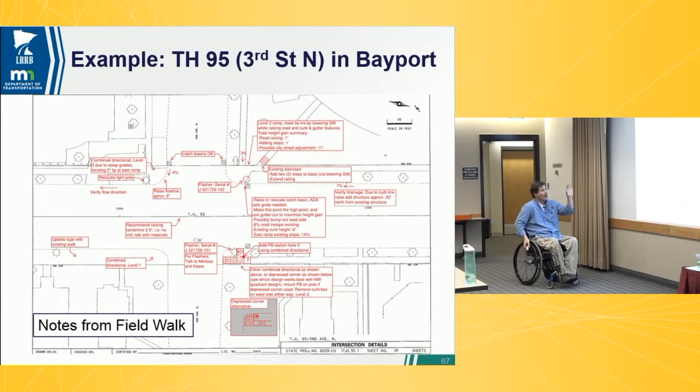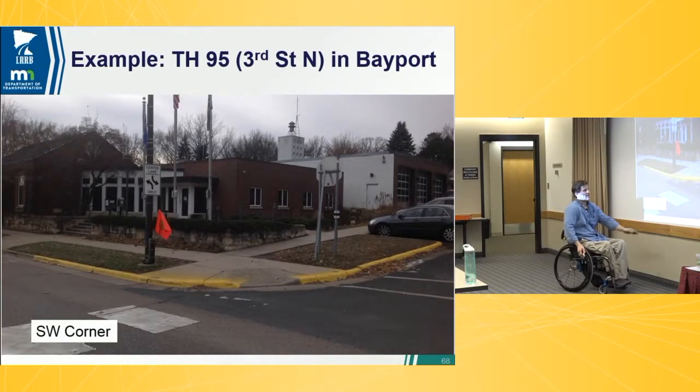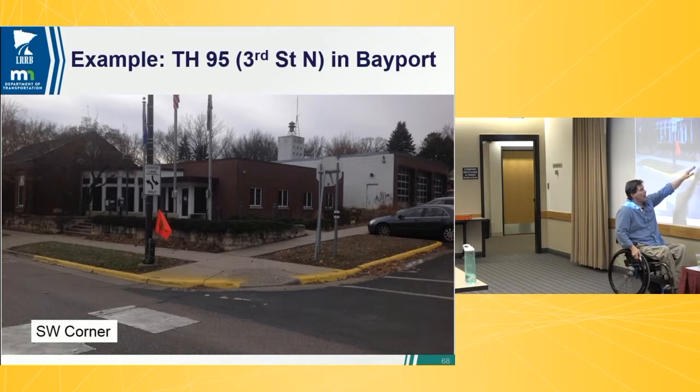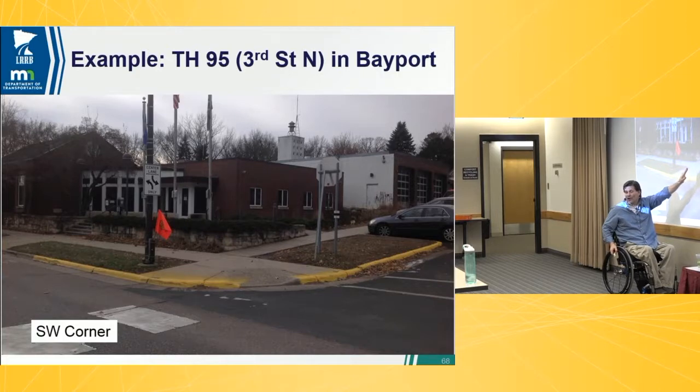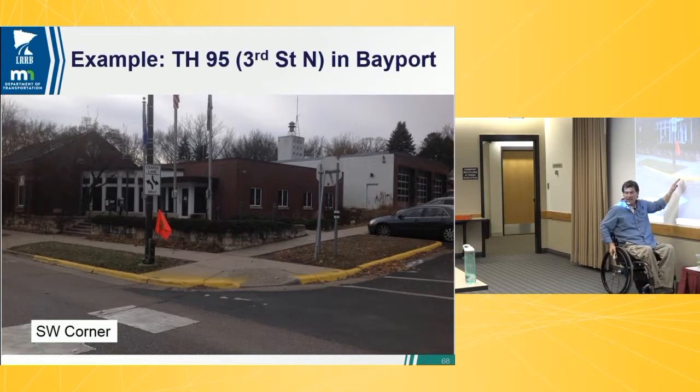So yes, here's our recommendations. We'll see what they say. This is the City Hall corner. Again, this is an 8% slope going uphill from this sidewalk already, so I'm not going to chase that. I can't get any grade out of there. I can't improve it. It's already maxed out. So I'm going to use this as my construction tie-in. This is also 8% coming down here.